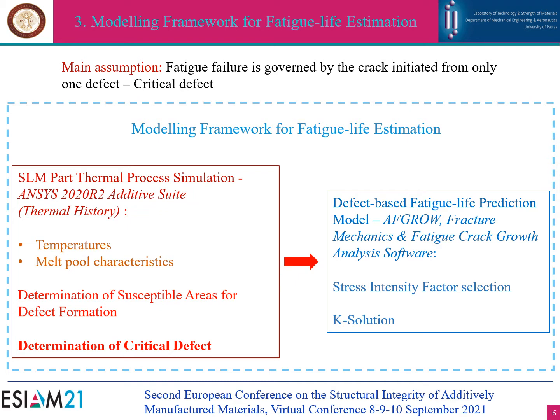This framework accounts for the presence of defects in AM materials and can potentially be expanded in the design of SLM parts. The main assumption of this modeling approach is that fatigue failure is governed by the crack initiated from only one defect, which is known as the critical defect. The main sections of the presented modeling framework are